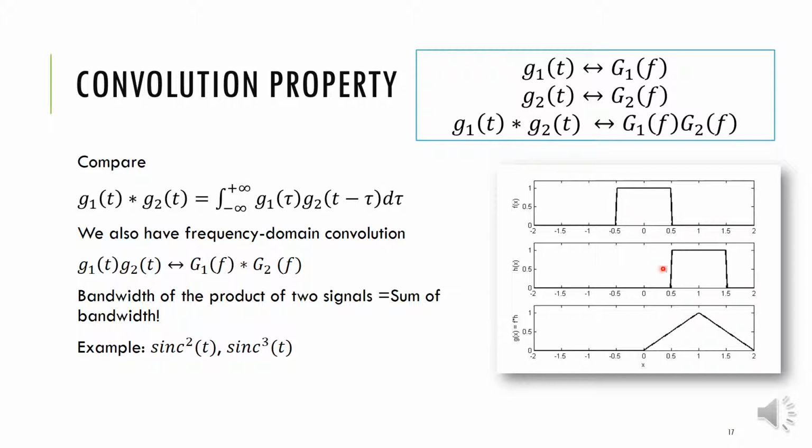If we have two basic signals, how do we get their convolution? Remember that the area of the resulting convolution equals the product of the two areas, the starting point equals the sum of the two starting points, and the end point equals the sum of the two end points. For example, 2 is 0.5 plus 1.5. To get the exact shape, you have to perform the convolution.